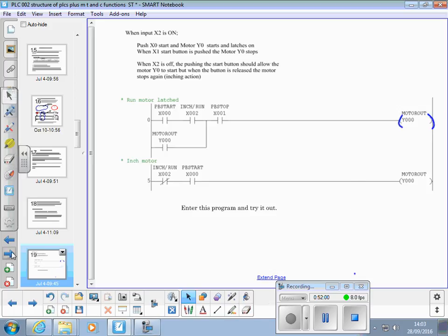The way I should cover that is that in the normal condition, that contact is closed. While my finger's off that red button on those switch boxes, that contact is closed. Because the X1 input is on. When we get over on the practical, call me over and I'll show you what we mean.